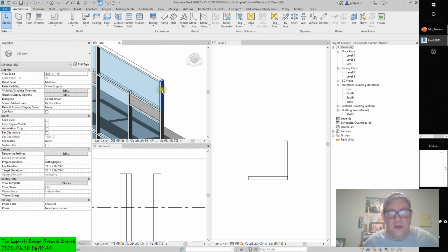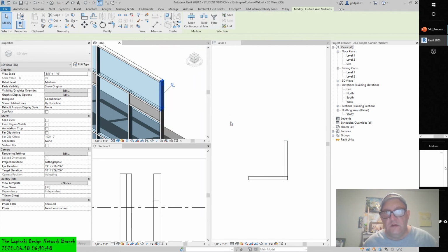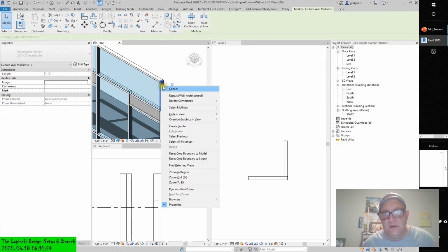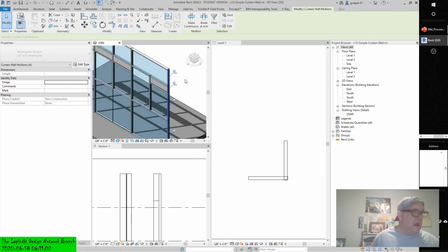you can change it by right mouse clicking. You can help yourself select by selecting mullions on vertical grid, right? That's all of them. Or you could select this one wall mullion segment, and you could select mullion on grid line. That's the grid line of that mullion, or, again, I'm going to reiterate it, I don't like the word line. The overall kernel definition. You're defining the curtain wall. Where are you defining it from? The curtain wall definition.